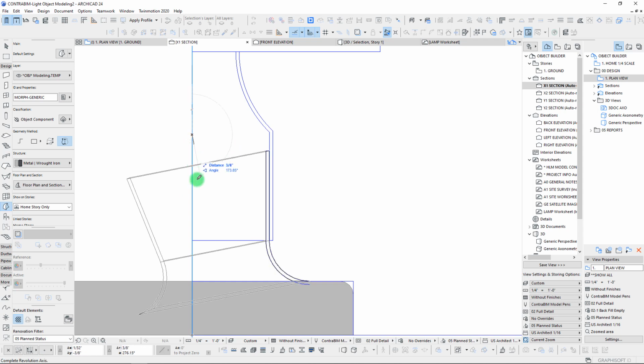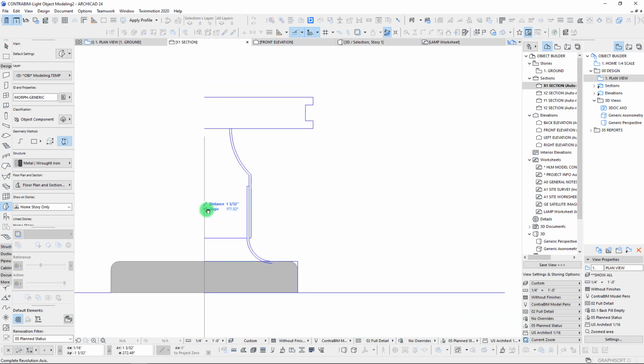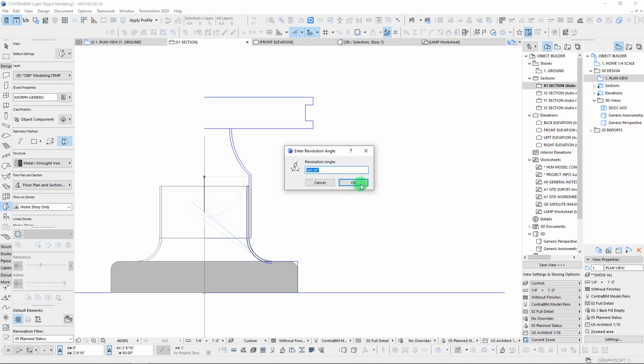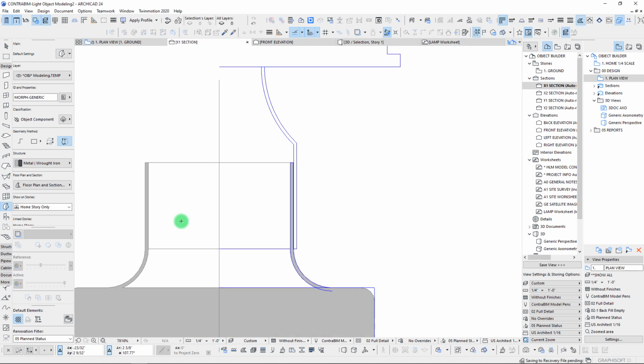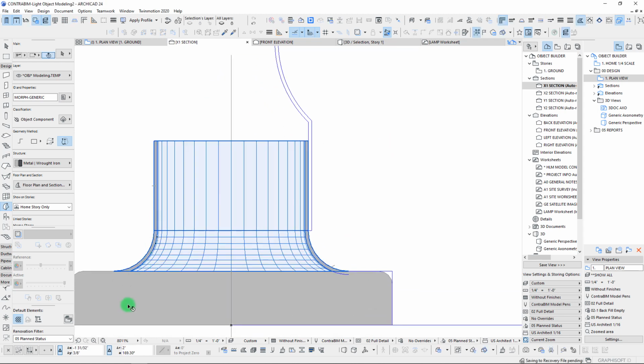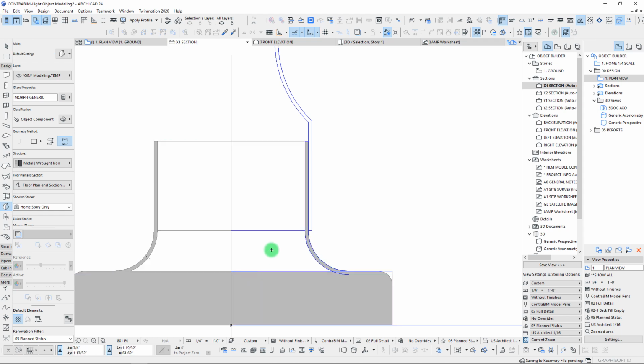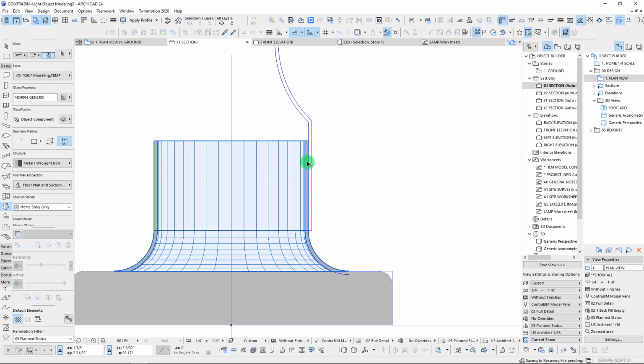And so we're going to be clicking on the center line, and then you can see as soon as we click, it's going to ask us where we can complete that center line axis. And so obviously we just want to create another point directly on here. And then we set this to 360 degrees, and there we are. So we now have that component, and we can essentially just merge it together with our base if we wanted, or we can leave it as separate elements for now.